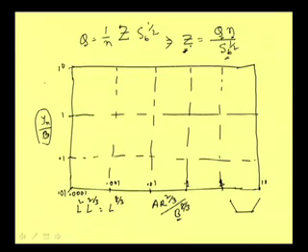So, for a circular section we can plot here y n by D, that is the diameter of the circular section. Well, this D 0 normally is used, and then here also it is plotted either this or A R to the power 2 by 3 divided by D 0 to the power 8 by 3. What is D? When we take a circular section, then this diameter is considered as D 0. Okay.